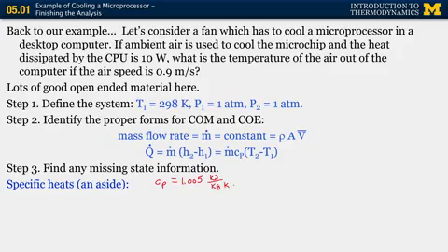Now, moving from this part of the equation to this part of the equation, remember we invoked the ideal gas assumption, the ideal gas model. I'm going to show you some more information on how to check if an ideal gas approximation is correct. At atmospheric conditions for air, it is. No worries. Remember, we went through the exercise of what types of conditions would make us start to worry about ideal gas approximations: high pressures, cold temperatures. So we're not too worried in this system. In another example or two, I'll show you how to check that rigorously.